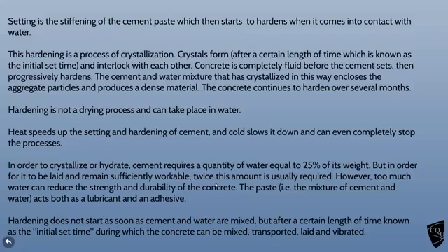Hardening is not a drying process. It can take place in water with the right mixture. Setting is an exothermic reaction, so it'll actually feel warm to the touch. Heating speeds up the setting, so hardening starts as setting's continuing. Interesting point here that hardening takes a long time.